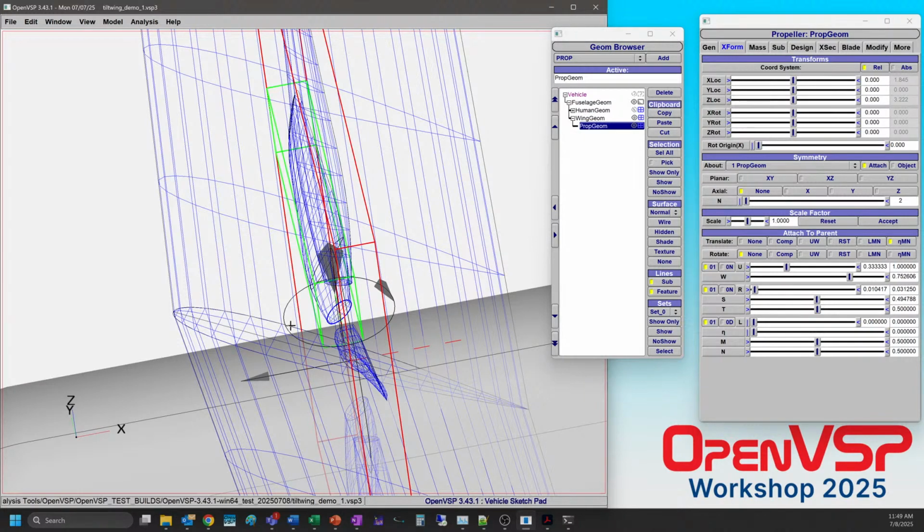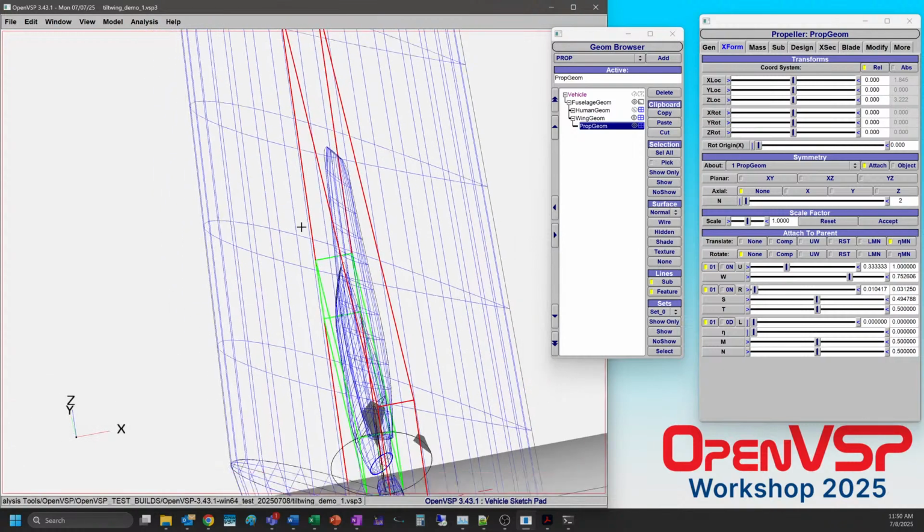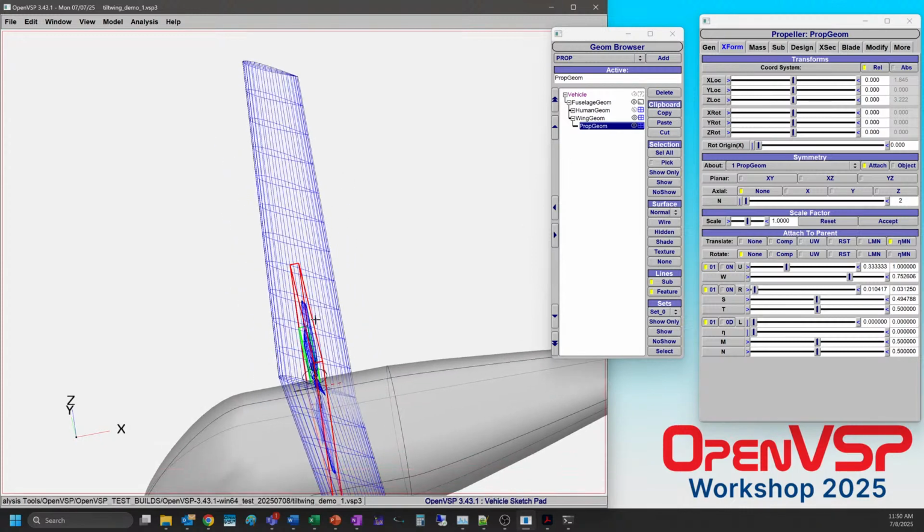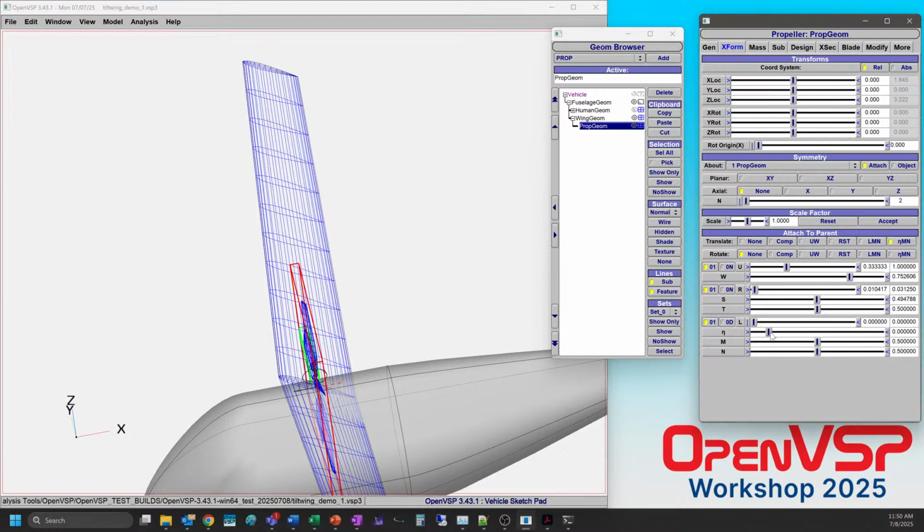And then because this is essentially a one-section wing, 1/3, 2/3 is all the way out here at the tip, and then 3/3 is the end. So if you happen to have your coordinates based in something like U, if you split the wing, all of a sudden that U coordinate changes. The eta parameter lets you place it along the wing and it stays fixed. So notice how all these are updating.